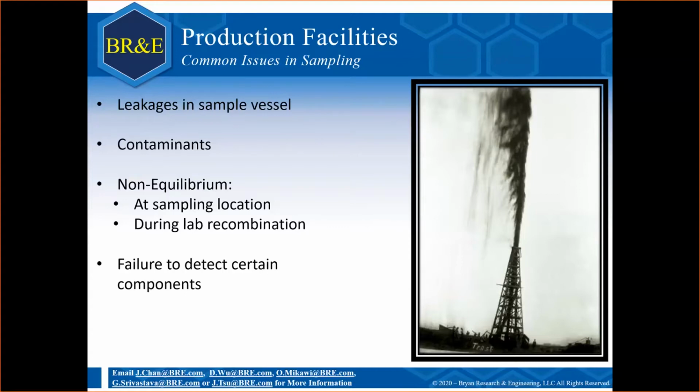We know from experience that that's not the case. We have entire facilities dedicated to removing acid gases from the liquid phase, particularly stabilizers that are used to strip out H2S. So if our lab is telling us there is 0 H2S in the liquid phase, that can lead to a severe underreporting of the overall H2S content in your system. So to deal with these, we're going to show you on ProMax how to account for these errors and what different types of errors can do to your final result.